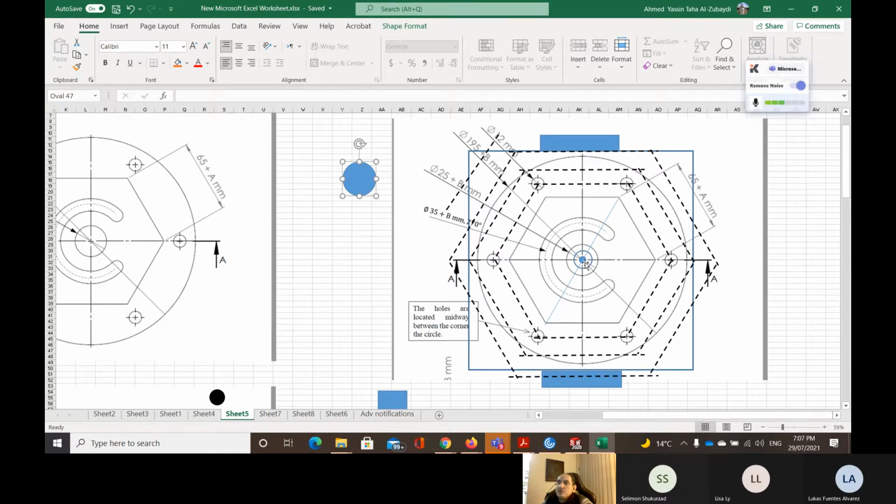Now we choose to have the datum point in the middle. Selecting the datum point will depend on the following things. First, in general, the datum point should be at this corner, the bottom left corner. Why use that? Usually the vice is not going to be here. It's going to be on these sides, always to the left and the right. So I just tried to explain to you why we have the datum point at this place.